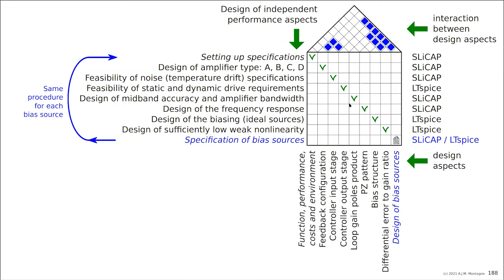The bandwidth is more like the impedance and the frequency response of the bias source. If biasing is only required in a limited frequency range for our amplifier to work, then maybe our bias sources can have parasitics. Maybe we can even use electronic inductors for that purpose.